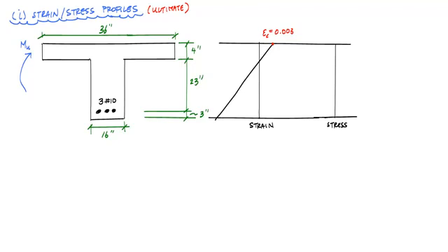Where it's 0 is where my neutral axis location is here. This would be c, and a, the depth, and my steel strain would be here, this epsilon s. This would be my strain in the tensile steel right here, and that's something that we need to figure out.